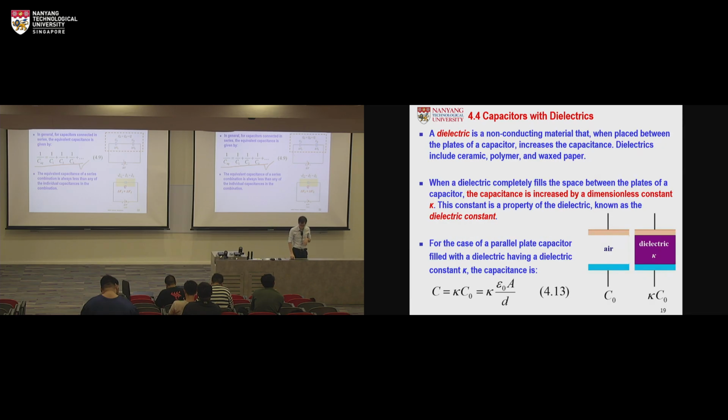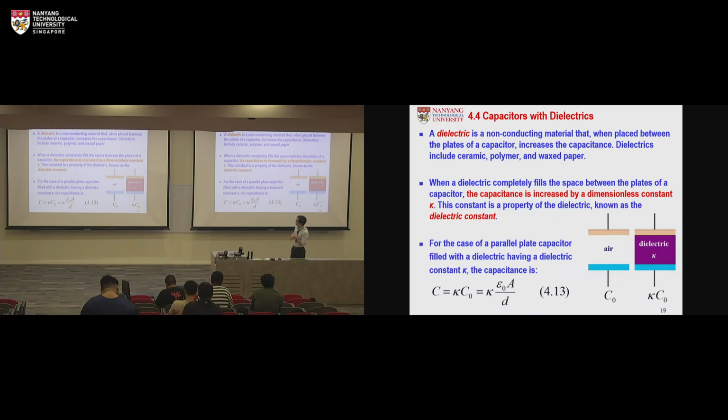Well, some other relatively minor topics is this dielectric constant, which basically, if you change the insulator in between, you will also change the capacitance. Typically, we are talking about the insulator being air. There can also be some other insulator. And here, the key parameter to define the difference is the so-called dielectric constant, this kappa.